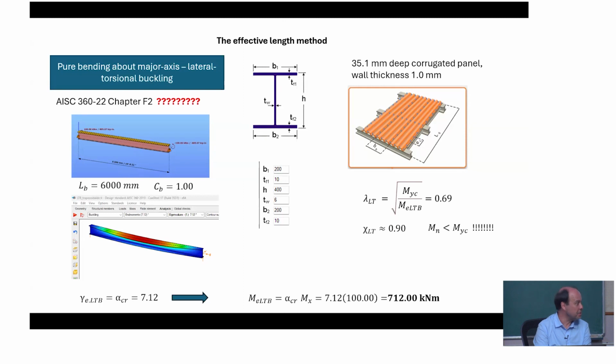So again, this typical assumption, I put a sandwich panel or a trapezoid and I don't need to check anything, is not necessarily true. It has a big impact. Finally, the LTB strength will be 10% less than the cross-section strength. Very often people just believe it, and there's typically no calculation. In some standards, there are formulas which define minimum parameters, and then you are allowed to disregard, for example, LTB. So if you are sure that your panel is strong enough, then you can disregard LTB. How precisely these rules are defined is difficult to know.